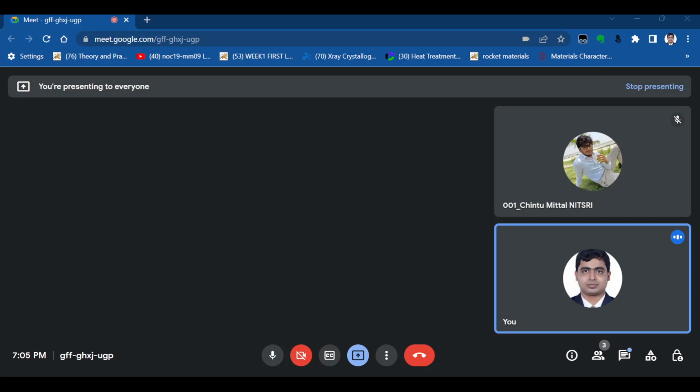Okay, so first, how do we draw this Mohr circle? First we take this sigma xx value and this tau xy value. One we take in the up direction and one in the down direction. Suppose this is our sigma xx value. From sigma xx we go in the downward direction for tau xy, whatever its value is, and then I look at this point.